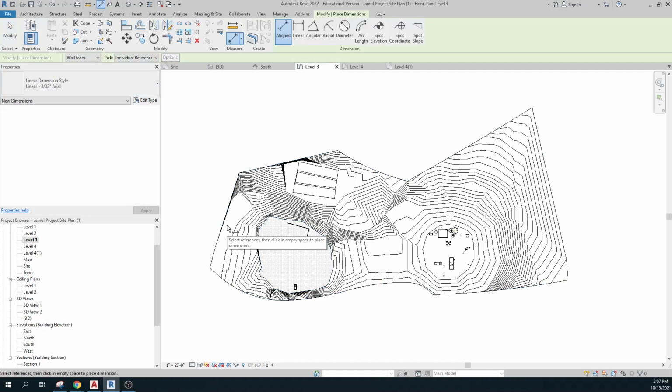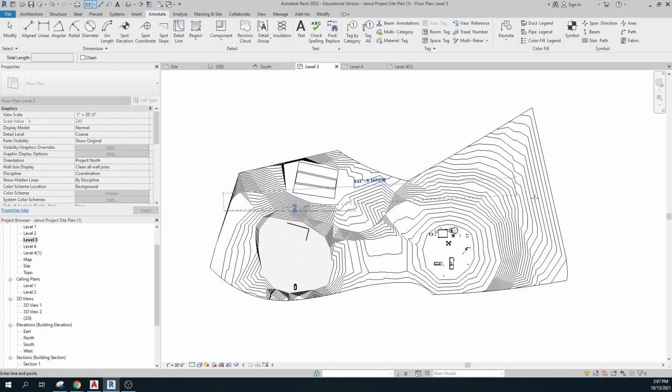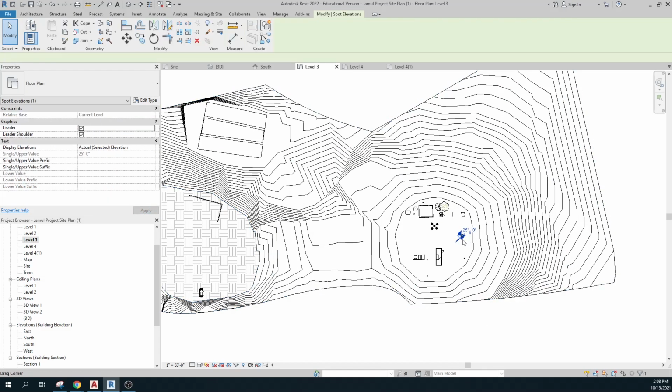But you know, if you're trying to figure out how far this is, this is like 700 feet. So I probably want 1 inch equals 40 feet or 1 inch equals 50 feet. So when I put it on a piece of paper, it looks a little better.